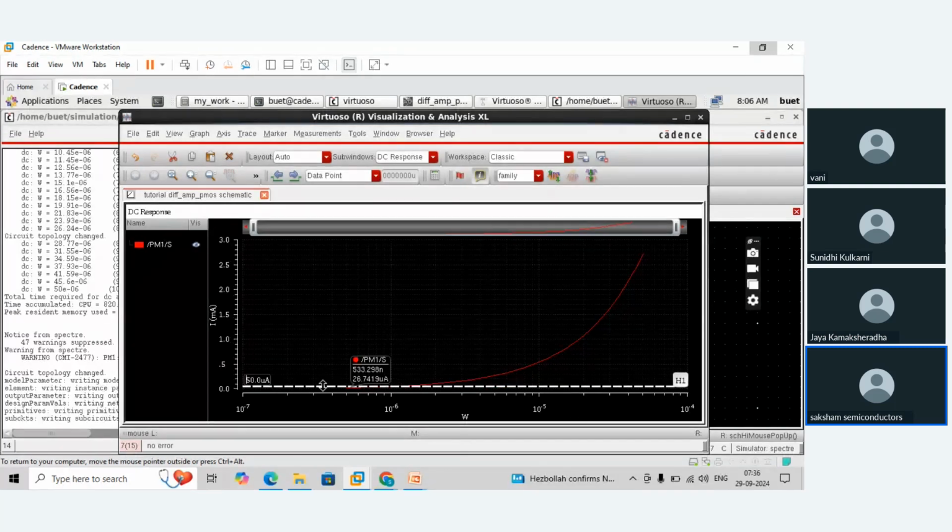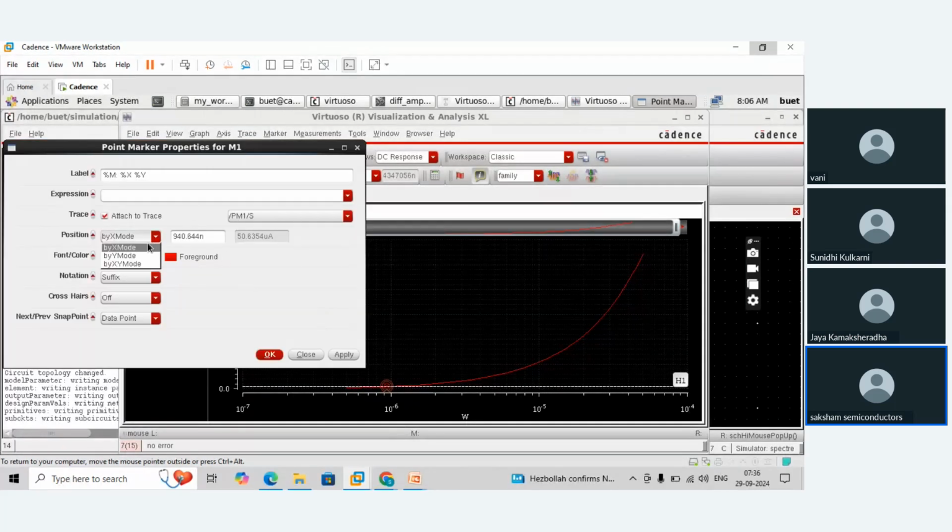Yeah, now you go. Now that horizontal line is passing on this particular curve. So I'll just place a marker where it is exactly 50. I'll just move around the cursor until I see the 50 over here. And then I press M, and then I say Q. And there is always an option where you can change this marker value to an exact value.